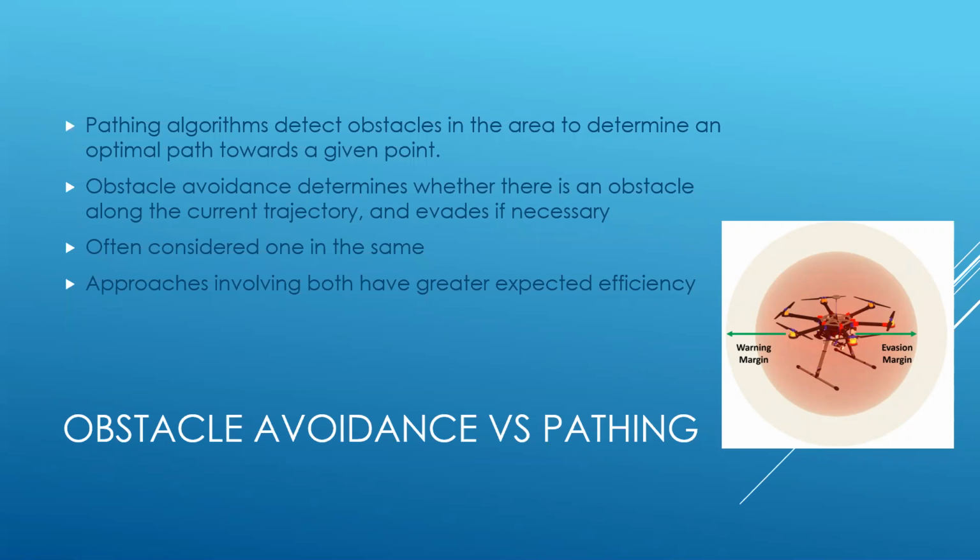For the sake of simplicity, suppose that there exists a UAV system that runs the pathing algorithm 5 times per second. Let this process compose m computational time. A large amount of computation is used despite the fact that the path of the drone cannot be expected to change many times within such a short interval. If an obstacle avoidance algorithm rather than a pathing algorithm is invoked in place of 3 or 4 of these iterations, the total computation spent is reduced from m to 0.49m or 0.32m respectively.